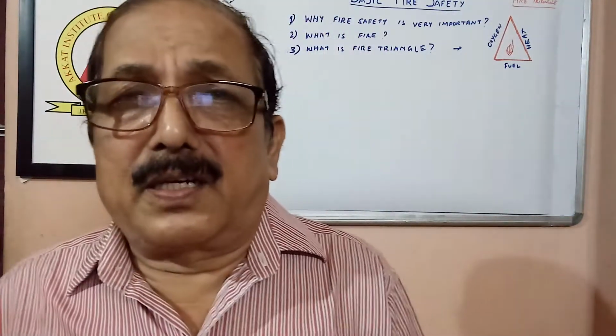Next one is electricity. Whenever we are talking about electricity, people say that wherever a fire occurs in a building, electricity is the culprit. If I ask what was the reason for a fire in that particular building, people used to say it was a short circuit. Exactly, that may be correct. Electricity is one of the main culprits for making heat energy, because according to the electricity rule, whenever current passes through a conductor, the conductor is getting heated up and the equipment is also getting heated up. The formula is I squared R T: square of the current into resistance into time. So electricity is another example of generating heat.